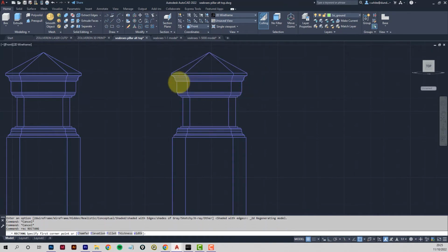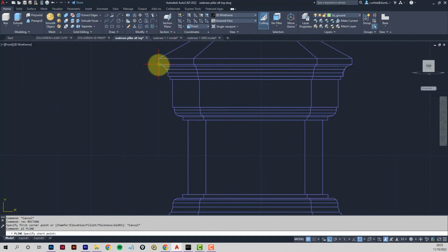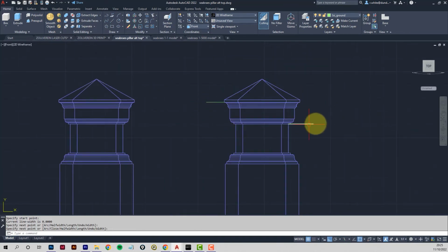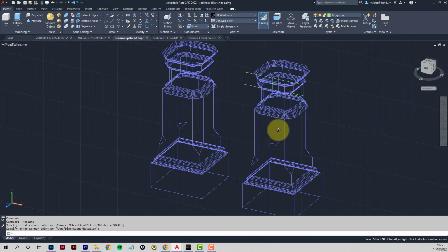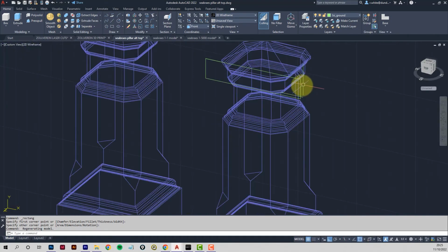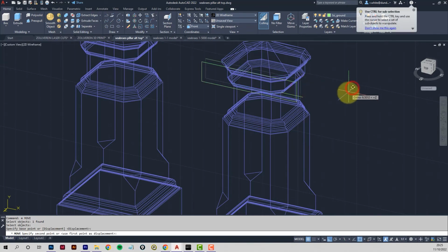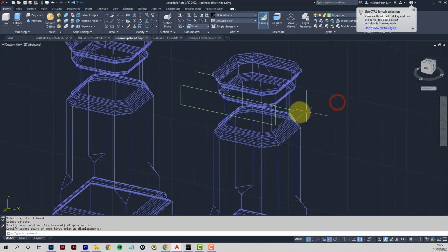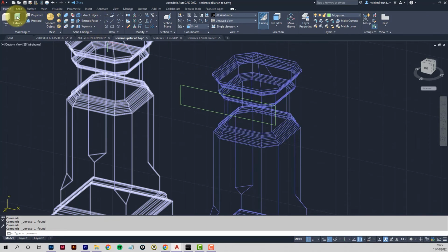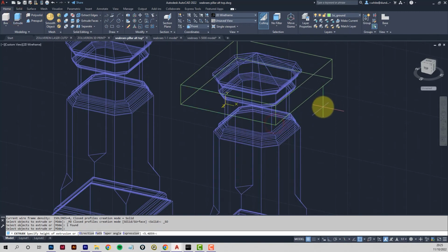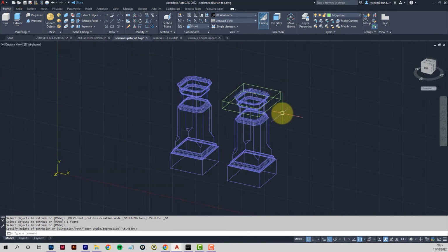Okay, so what I'll do there is just draw a polyline out from here, and a polyline out from here, so that I can put a rectangle in that area. So I'll just put a rectangle there. Okay, and then look at that in 3D. I'll pull this towards me. I've got ortho on, so I'm just pulling that box towards me. Let's just get rid of those two, and then extrude that back the other way, as long as it goes right the way through the object.